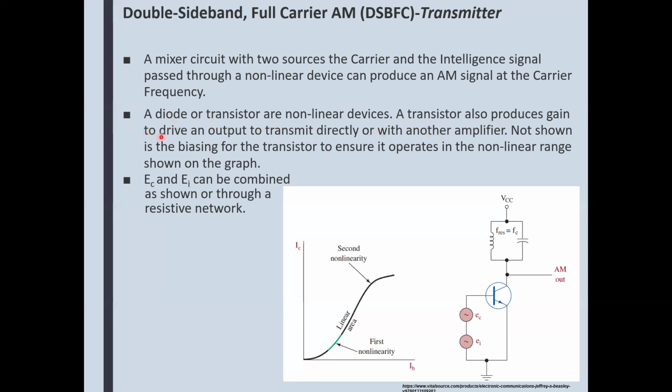also produce signal gain. Why do we need a nonlinear device such as a diode? It's just to eliminate one of the sidebands, because we don't need to listen to both of them, because they carry the same information. Plus, if you look at the envelope that we produced by combining those two frequencies, you are going to notice that the upper sideband and lower sideband are out of phase, 180 degrees. So if you combine them and put them into some sort of a device, you will hear nothing, because they will cancel each other out. So we need to cut one of them out.